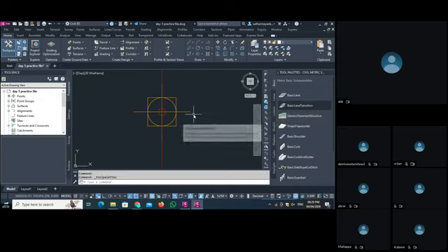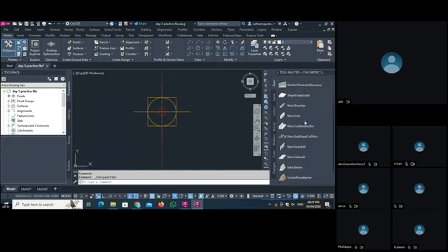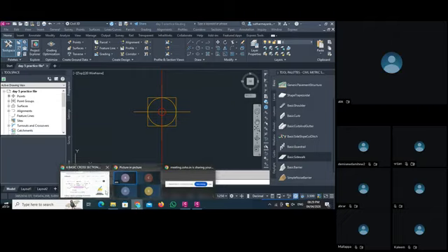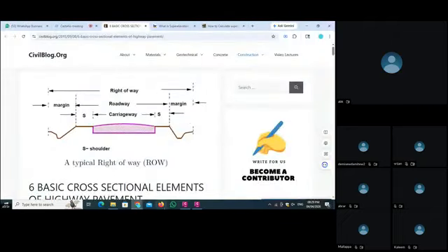So if you create one road and you want to stretch the road, at that time you select this as your lane. This transition lane goes along with the lead width, whatever width you give the lane. So many types of basic lane are here, shoulder is here, curb is here, curb and gutter, side slope and cut ditch.